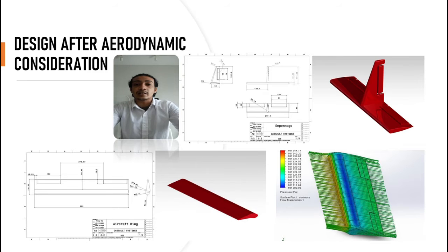And for the detail, we have some considerations and based on our reference shape, which is the Pilatus plane, our team decided to use the unbalanced cross-section shape. The reason is to provide stability during flight and directional control. One of the advantages is to get less loss while we are flying.